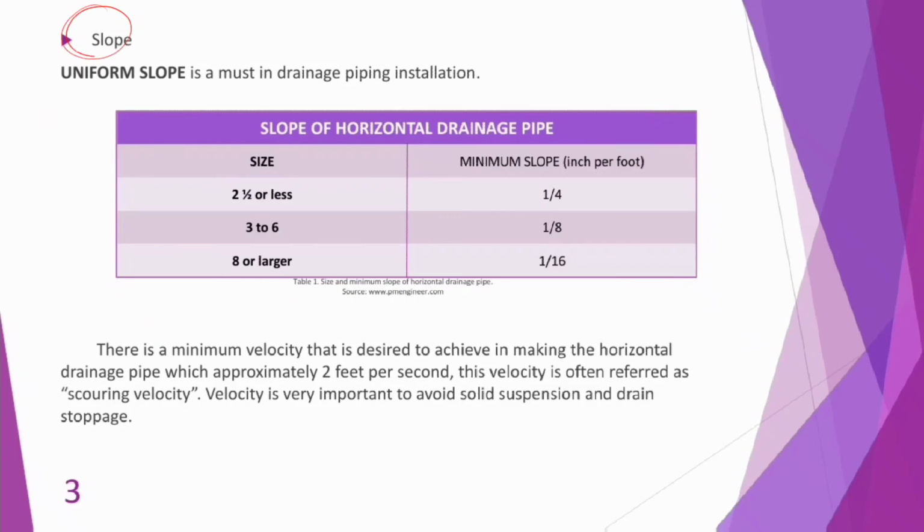Proper slope of drainage gravity and sewer pipes is important so that liquids flow smoothly, which helps transport solids away without clogging. Sabi, ang pagkakaroon daw ng maayos at magandang slope of gravity drainage and sewer pipes ay importante sapagkat ito ay nakatutulong upang mas maayos na dumaloy ang liquid sa ating mga pipe at nakakatulong din upang matransport yung mga solids na maiiwasan ang pagbabara nito.